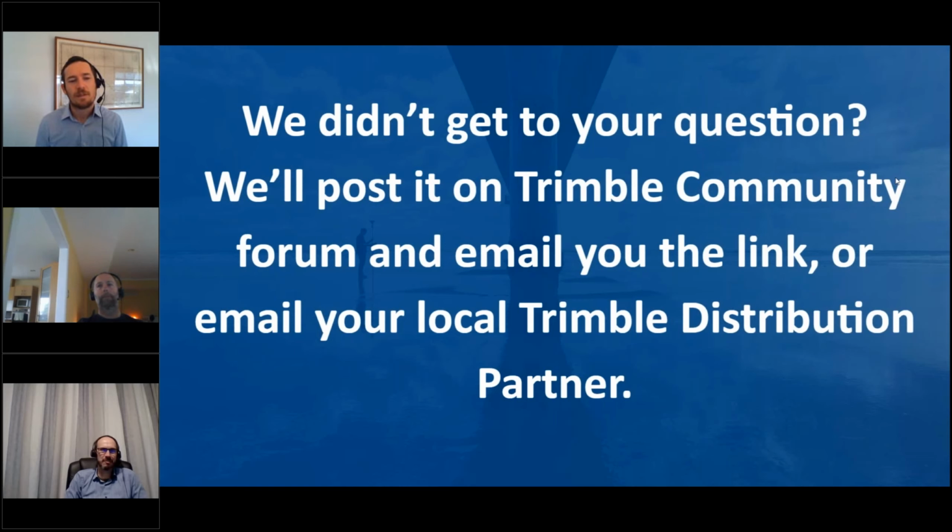The other thing you can do, which gets back to having the trial version of the Trimble Access emulator on your PC, is open up the job in the emulator and change the geoid model to the full one if need be. Or as Neil says, you can have your subgrid and load that into Coordinate System Manager as a geoid in its own right.